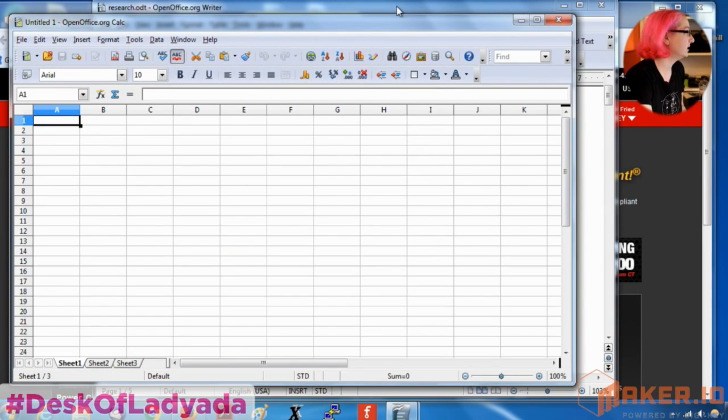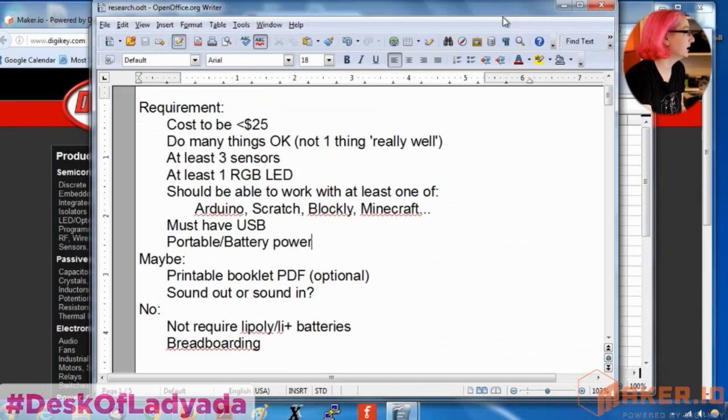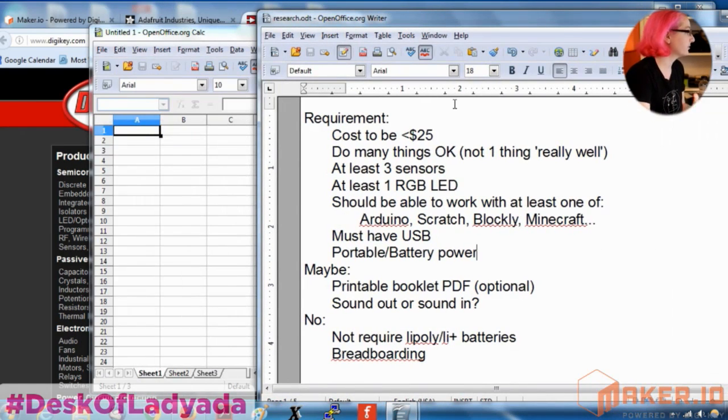You don't have to use a spreadsheet. If it's simple, it's okay. But let's pick out the first most important question. The first question you've got to pick out is, what is your core microcontroller, microprocessor platform? You don't have to stick with the one you start with, but it will take you a very long time to get used to whatever microcontroller or microprocessor you're using. So if you can pick that ahead of time, that's a really good idea.